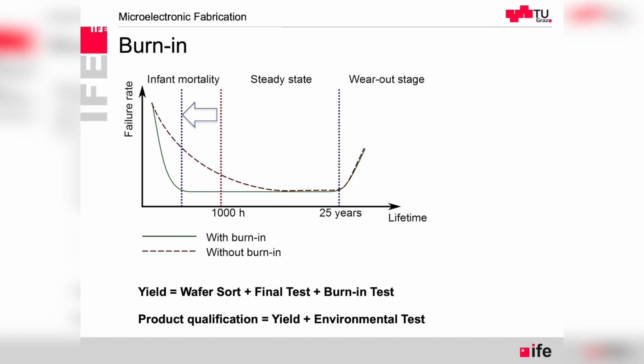So this reliability is also subject to design, and how we design the lifetime until the wear-out stage happens and the failure rate is increasing again. We would like to have it as long as possible, but again, it's a question of budget, how much effort we put into the reliability. But generally, this so-called bathtub curve, that first it's high, then low over the lifetime, and then the wear-out stage high again, is the typical reliability curve.